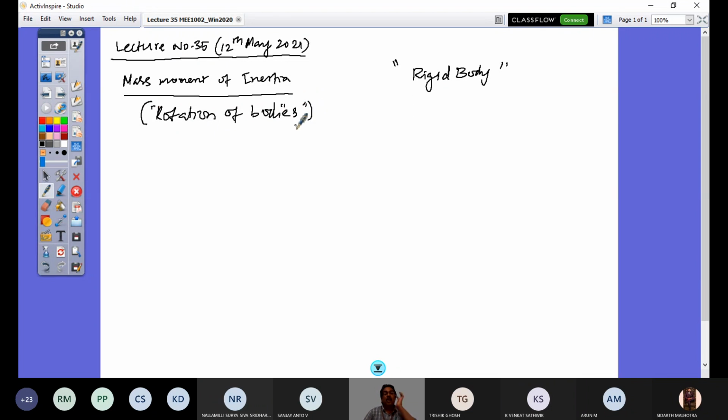Right? So the resistance offered to start the rotation, or the resistance a rotating body has to stop the motion, is dictated by mass moment of inertia. You can see that element appear in the governing equation of motion of rotation given by the Euler equation. Unbalanced moment present in a body would cause its rotation, I into alpha, where this I is called mass moment of inertia.